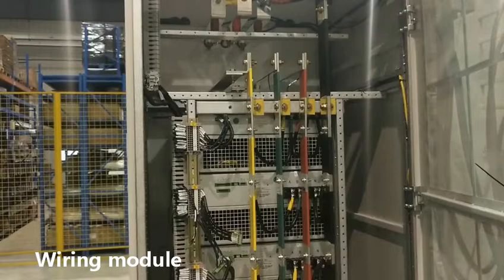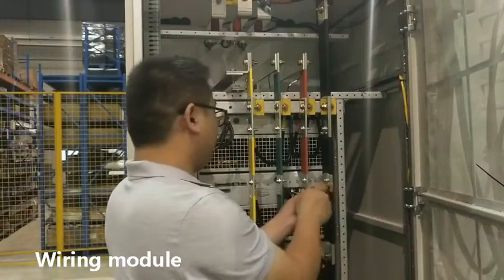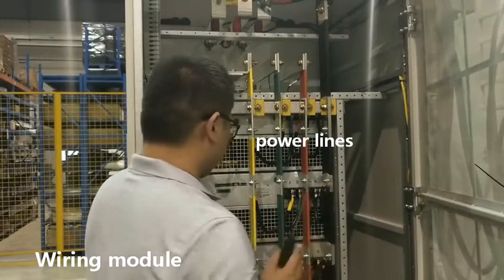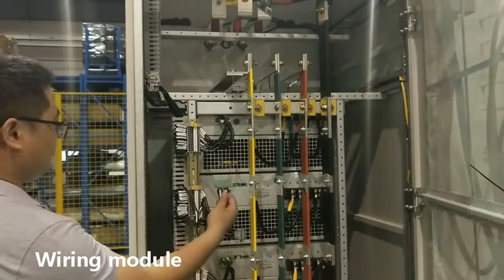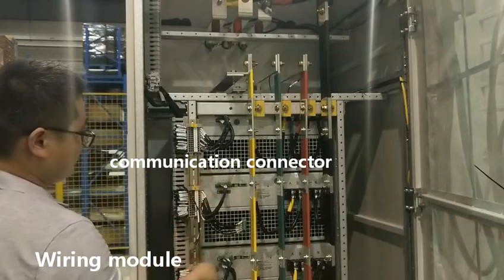After installing all the power cells into the cabinet, we will connect all the cables. First, the power cable: phase A, B, C, and neutral. Then we will connect the communication cables for RS-485 and CAN.